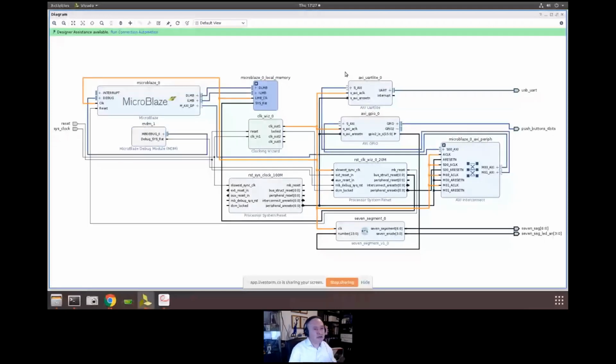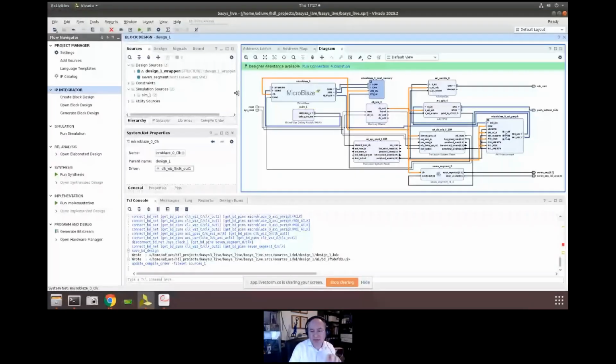Live projects, right? So we've got that. What we want to do is add our HLS IP core into the design, and what we've created now is a MicroBlaze processing system. So if we wanted to run Hello World, we could run Hello World. If we wanted to read the state of the buttons, we could read the state of the buttons. But as of yet, we've not got anything that's going to give us that video output path, or draw the game as we were showing.